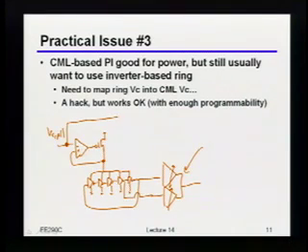But the good news is, it's kind of similar. I have to wave my hands furiously, but it's roughly similar. So what people will typically do is take that control voltage, feed it to that bias generator block, and of course to the phase interpolators themselves, and then just hope that those things are close enough that it works.